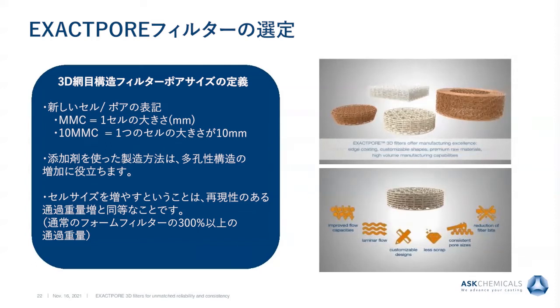With the design of the EXACTPORE filter, a new cell designation was needed. This designation was to be MMC, which stands for millimeters per cell. A 10 MMC filter would have a cell size of 10 millimeters. The additive manufacturing process allows ASK the ability to increase or decrease the size of the cell structure. With increased cell size, increased capacity becomes more repeatable. On average, ASK recommends a like-size filter from 3D printed to foam to have a 300% increase to capacity.